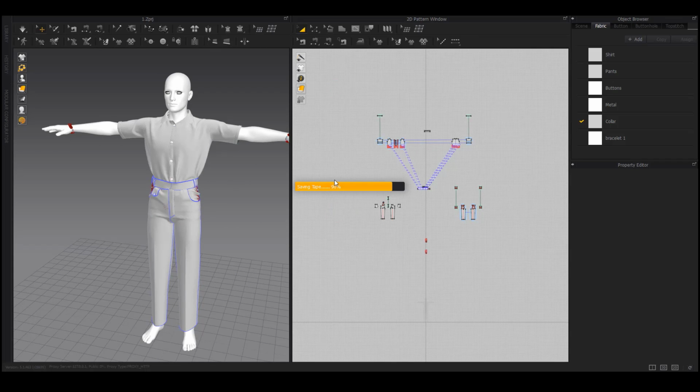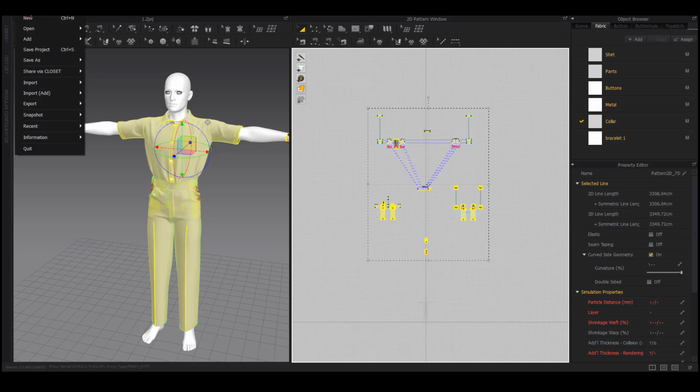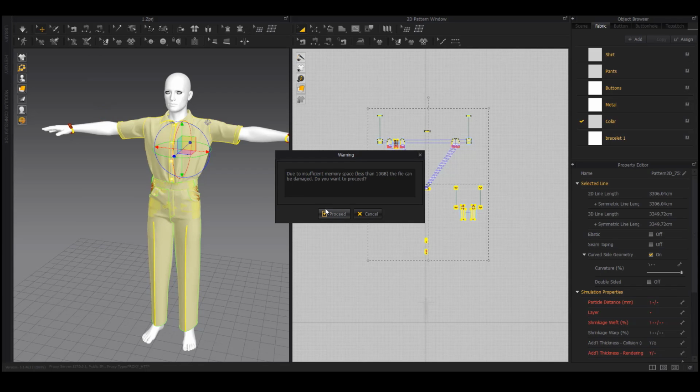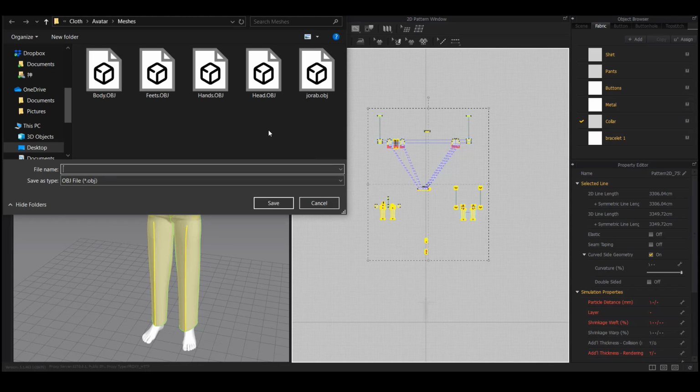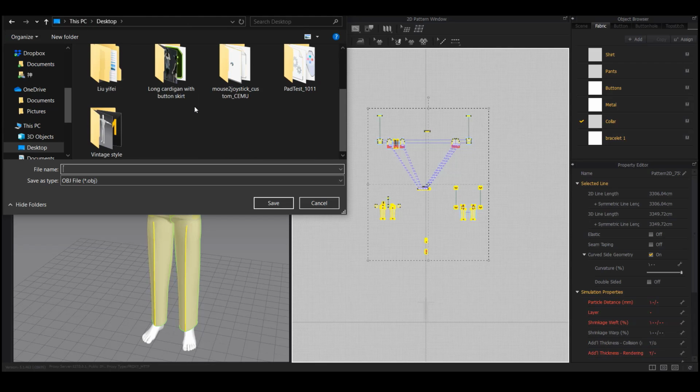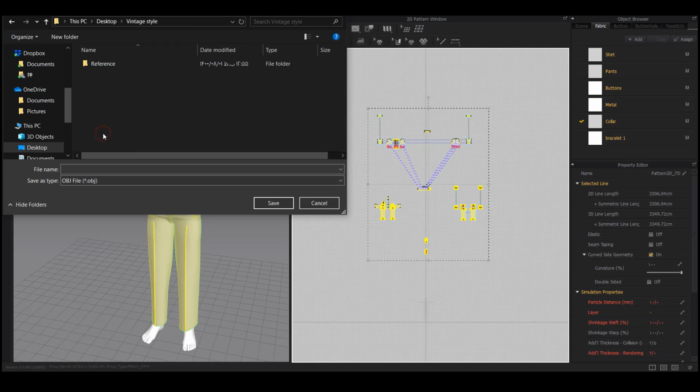After finishing the process, it is better to simulate again, and finally, the model is ready to output. Save the output as OBJ without characters. Select the single object mode, and choose one of the three modes, thin weld, thin unweld, and thick, based on our needs. In thick mode, the thick parts' UV is not defined.